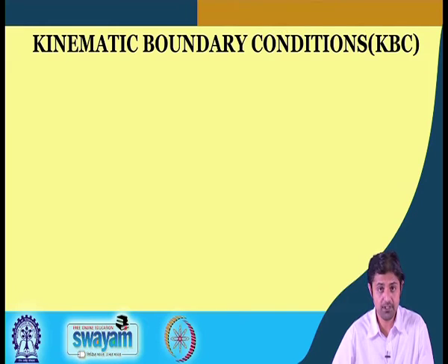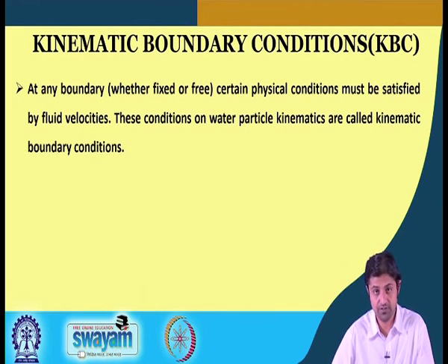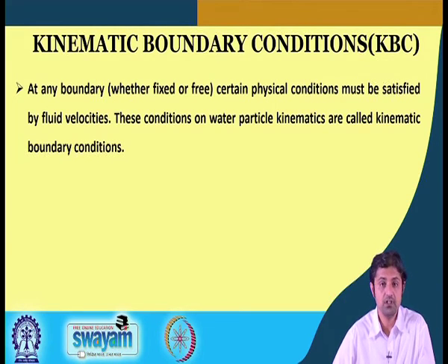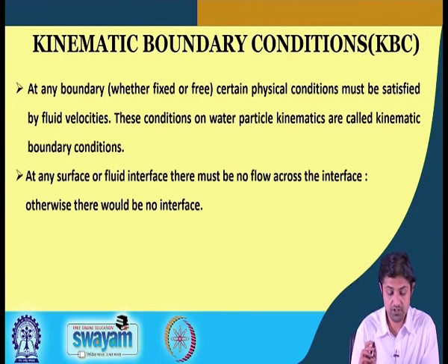One important property is the kinematic boundary condition. We are talking about boundary conditions. So what is our KBC? At any boundary, whether fixed or free, certain physical conditions must be satisfied for fluid velocities, and these conditions on water particle kinematics are called the kinematic boundary condition. At any surface or fluid interface there must be no flow across the interface.